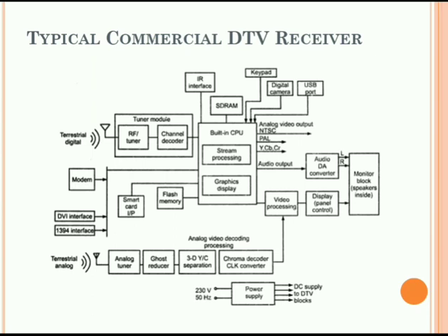The compressed video bit stream is given to the video decompressor unit, and video decompression is achieved by using MPEG-2 video decompressor. The decompressed digital video data bit stream is given to the video DAC, that is, the digital to analog converter, for D2A conversion purpose.